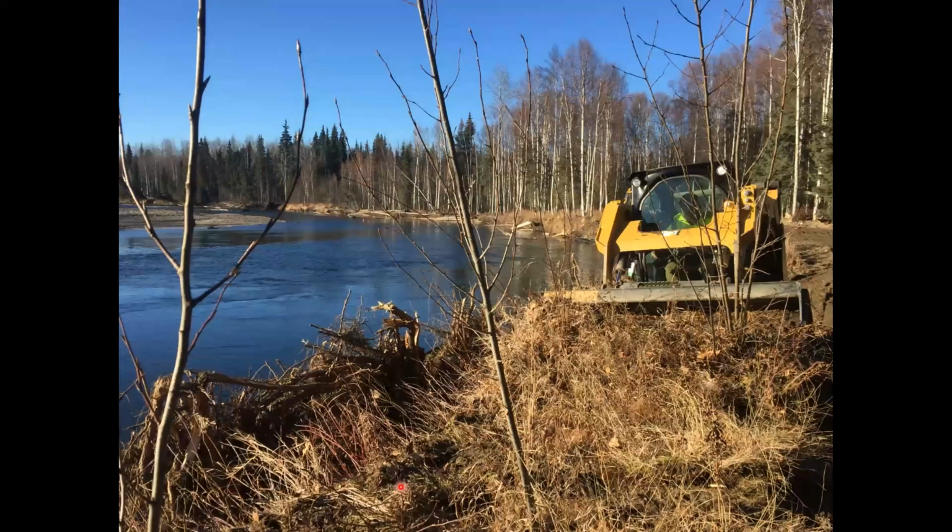And they elected to just use a vegetative mat that was as wide as the skid steer. So they just went with the skid steer harvest vegetative mat that was further than 50 feet away from the site. And so they just harvested it, brought it in. I'm guessing that skid steer's bucket is maybe 6 foot wide. And so their veg mat is coming 6 foot wide. And one thing I like to point out is they've got a lot of trees that they were able to harvest that hopefully will take off and help. So getting a really robust vegetative mat really helps on projects such as this.